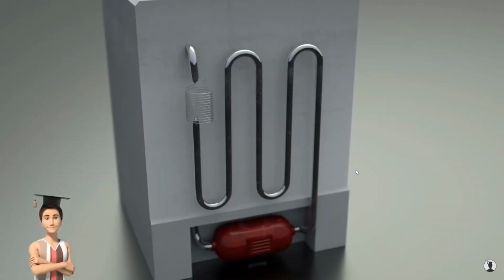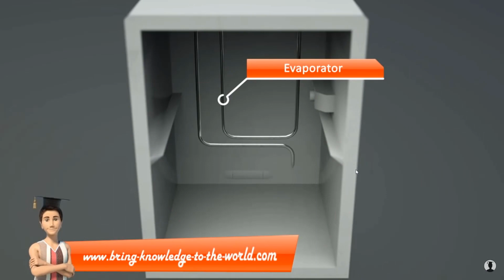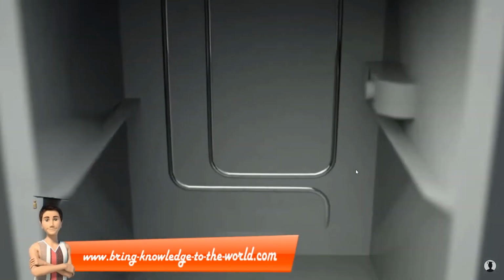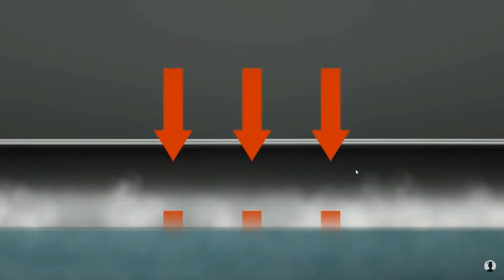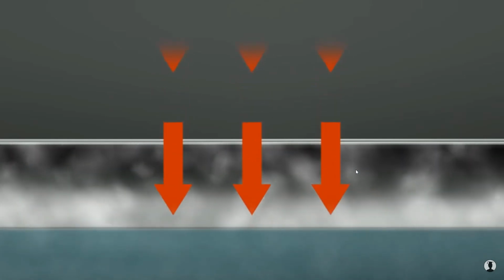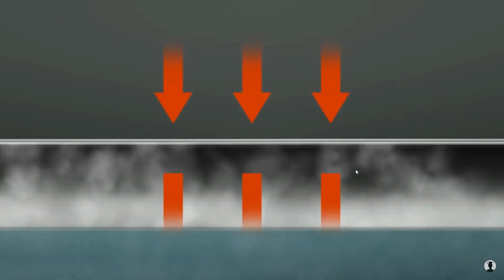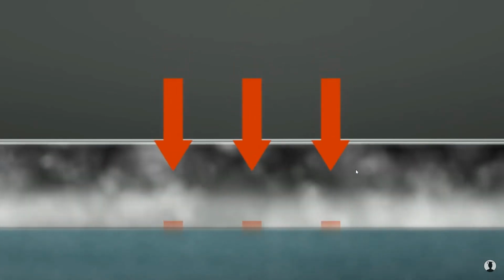The refrigerant flows through the evaporator within the fridge. Now, thermal equilibrium between the inside of the fridge and the evaporator takes place. As a result, the heat is transferred to the evaporator and the fridge becomes cold. While absorbing heat from the fridge, the refrigerant evaporates but doesn't get much warmer because the heat is stored as internal energy within the refrigerant.